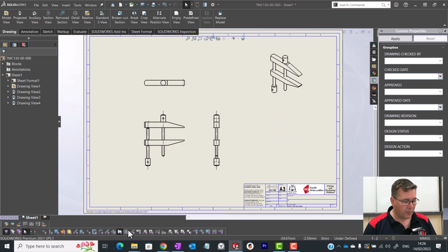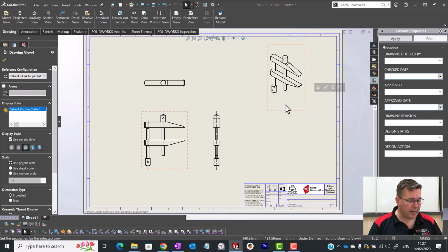Whenever I turn a filter on, you can either select the centerline filter that you add, or select this filter here to toggle filters off, which happens to be F6 if you want to use the keyboard shortcut. Right, so let's just finish up this assembly. I'm going to click on the isometric. I'm going to change that to a shaded.